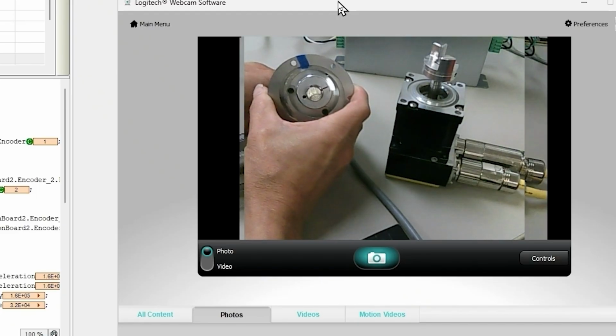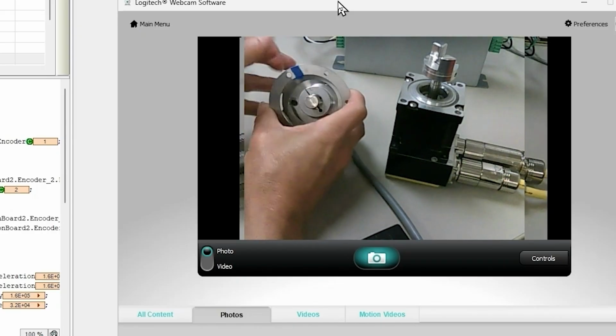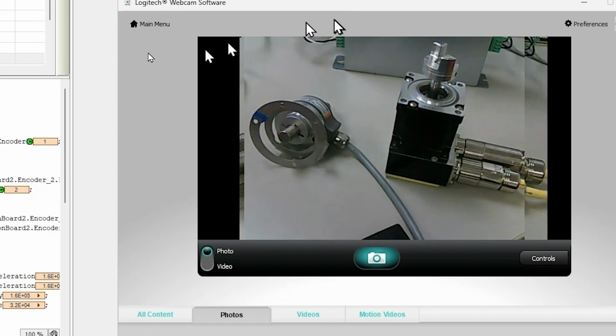The beauty of this is that the drive itself supports CODESYS programming, IEC 61131-3. And so it has all the programming capability, such as ladder program, CFC, and structured text, as you see on this side here. But anyway, let me go through the connections real quick on the PSD that I have here.